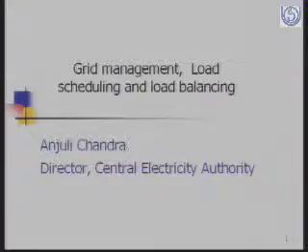These substations are very compact because the switchgear and other equipment is enclosed in gas, and it takes 1/3 of the space of an ordinary outdoor switchyard. So that is why we can go in for these GIS, especially in metro areas where land availability is difficult, and we can go with GIS underground also. So a 33 by 11 kV substation can be constructed underground also with the help of gas insulated substation. This is what I would like to tell you. Further, we move on to grid management, load scheduling and load balancing.